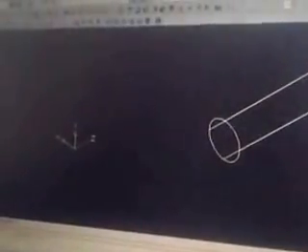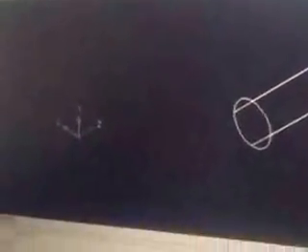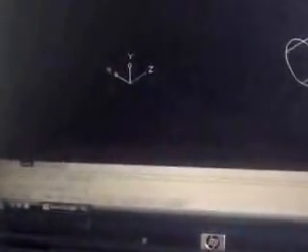I'll click on helix. Where is the helix? If you go through the command line to specify the center point of the base, I will give it 0, 0, 0. My helix diameter, same thing as the boat. I can give it 2. The top radius, I need 2.